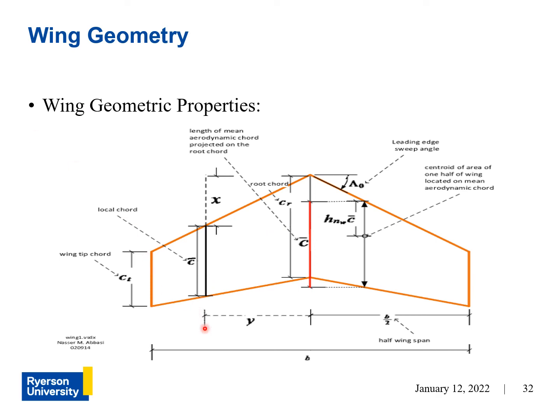At the mean aerodynamic chord, the whole wing has its aerodynamic center, like this entire wing, at about the same location as the airfoil located at the mean aerodynamic chord. So if you were to find the pitching moment of the airfoil at the mean aerodynamic chord, you actually find the pitching moment of the entire wing, not just at that specific cross section.